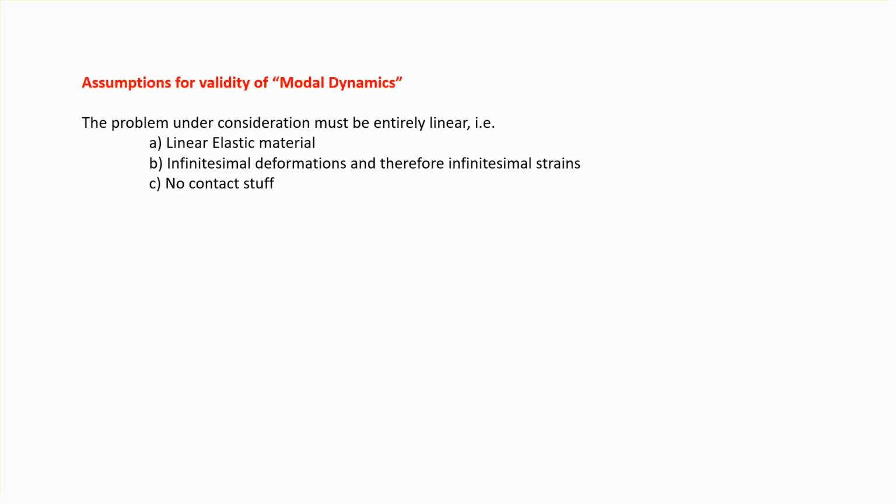Now, you have to be aware of the limitations for modal dynamics, and the problem must be entirely linear, both as far as material properties is concerned, as far as the strains are concerned, and displacement, infinitesimal, and no contact is allowed if you're going to do modal dynamics. And the reason is that this is based on the modal superposition method, and as soon as you say superposition, the problem has to be linear.